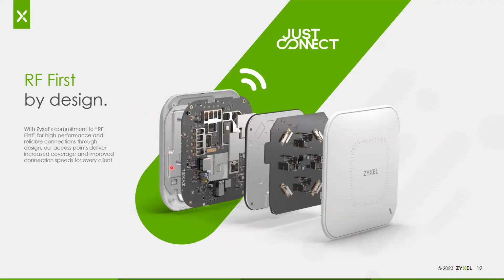Another thing that we do on our products here is we do not use any electrolytic capacitors. Those are capacitors that are filled basically with a little bit of cloth material and salt water, and they can dry out, they can leak, they can boil over, causing failure. So we only use solid state capacitors on our access points to make sure they can last a long time. Another area where you will see a difference is you will see a lot more shielding on the chips than you would see on some of our competitors' products.